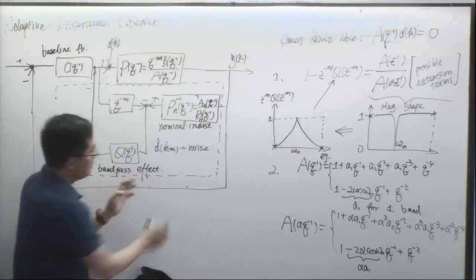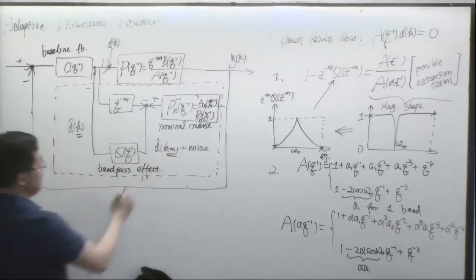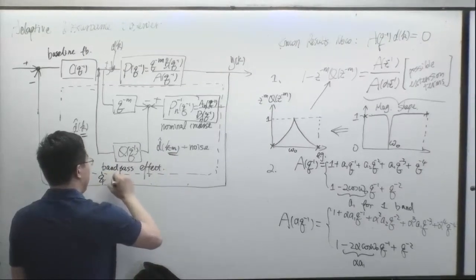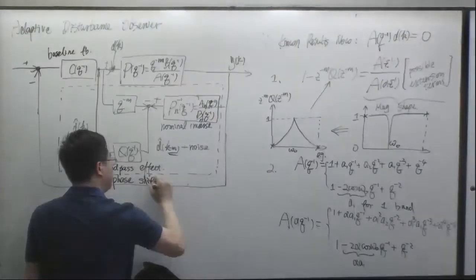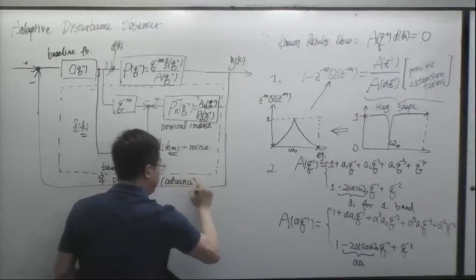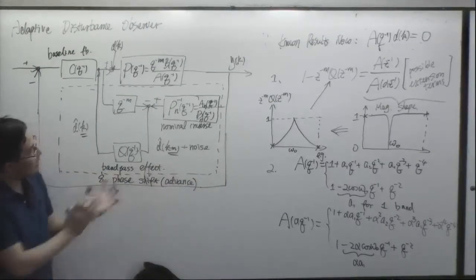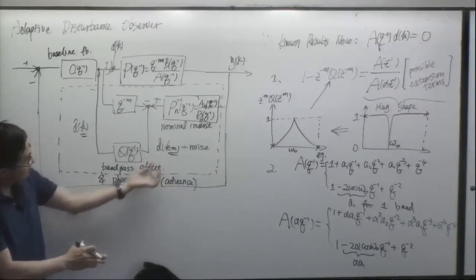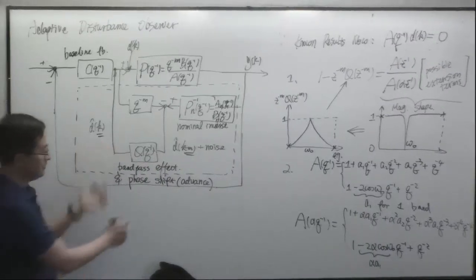And then second is what we talked about, this shift of delay operation, which acts to provide phase shift. More specifically, it is actually phase advance. So you have a delay in the signal here. It is actually going to be advancing the signal phase to make it correctly stamped at time k, counteracting the delay effect.